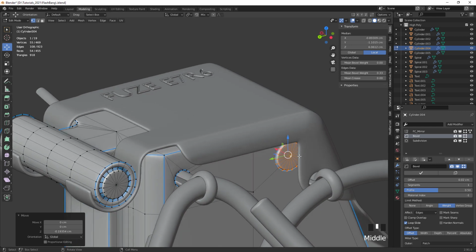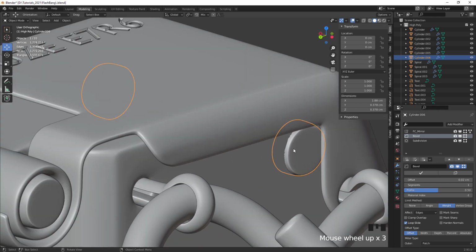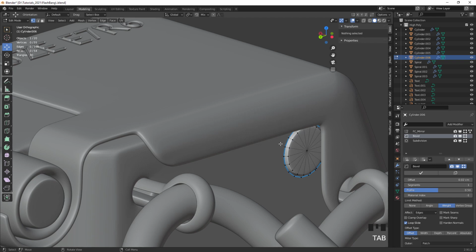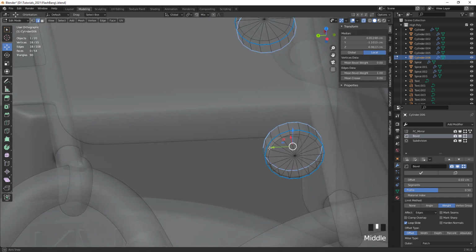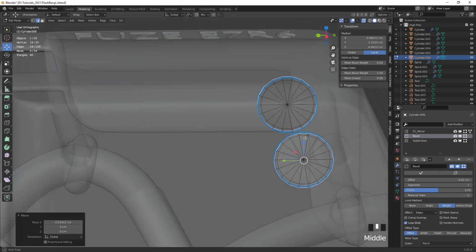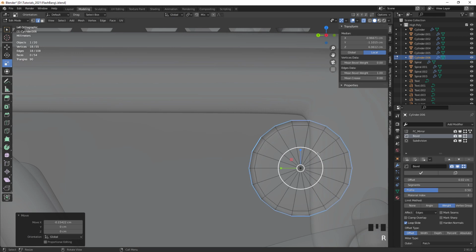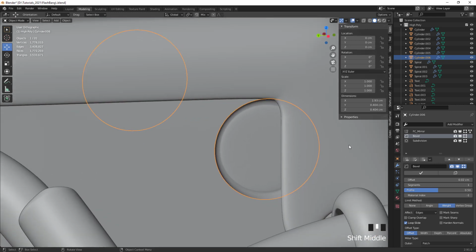Now this element here we can also separate out. And the cool thing with Blender is that it will always remember the modifiers that we had on it, even if we separate it. So since this is a detail that is only visible for our bake, for our normal map, I'm gonna push that back out here like this and then scale it up so that it looks like it has some depth here once we bake our normal map.